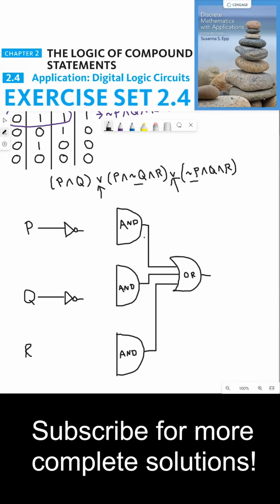Okay, so now that we have the latter half of the circuit, we need to figure out what goes in each AND gate. The first AND gate is going to represent P and Q. So we need the input for P and the input for Q. Now we have to be careful because these outputs right here from P and Q are the outputs of NOT gates, which is not P and not Q. So we want to make a split at P and at Q before the NOT gates. And that's our P and Q, and we need to bring those to the inputs of this AND gate. Okay, so that's our first AND gate.